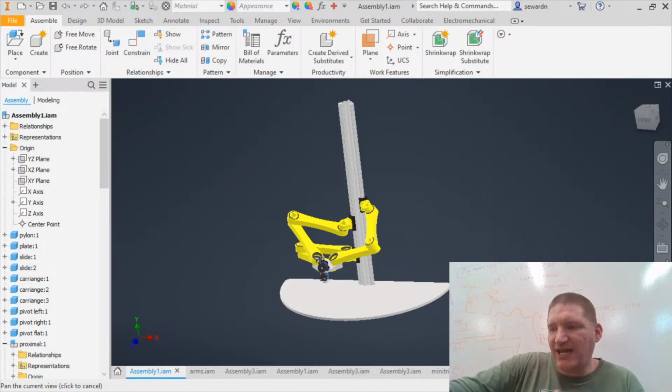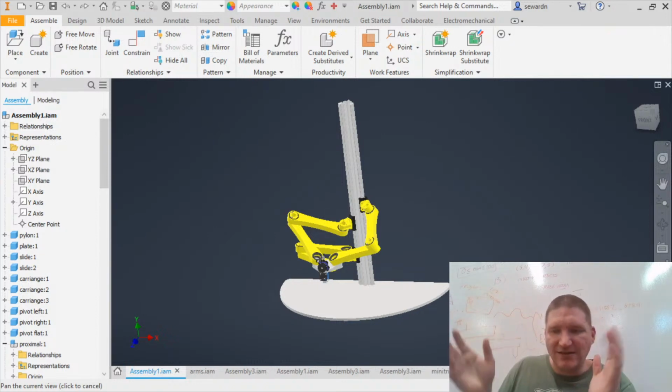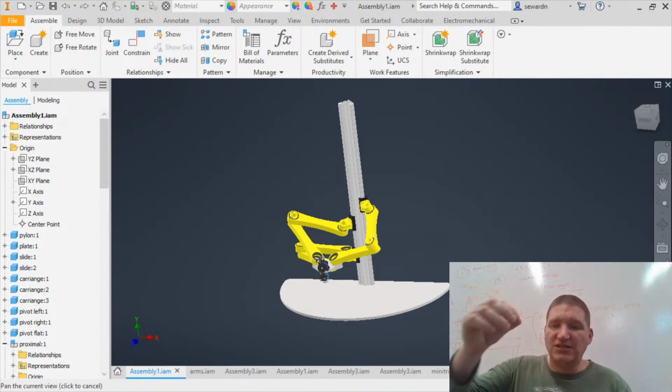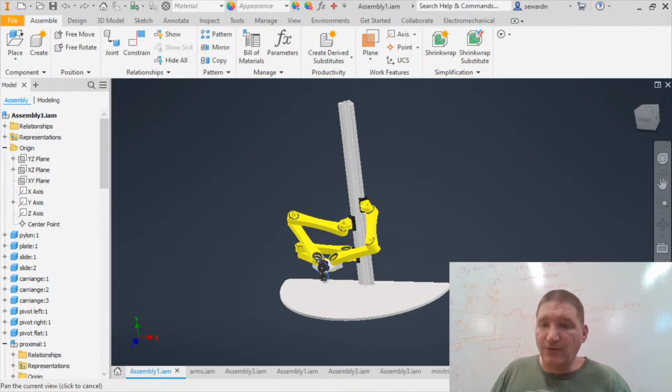I mean, yeah, if you had a servo drive you could make a cobot where you could push on it, and it could move out of the way and then move back. There are some really cool things you could do with feedback. But the most useful feedback would be on the effector, to actually know where the effector is. As far as I know, there's not really a good solution for finding that out cheaply to the precision that we need. So basically what we all do whenever we build 3D printers is we build it rigid, tell the steppers where to go, and hope for the best.